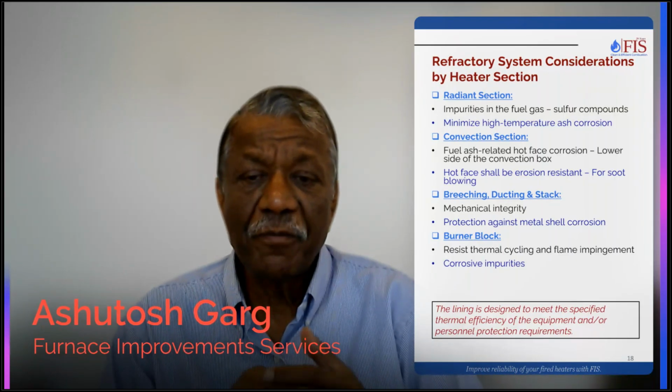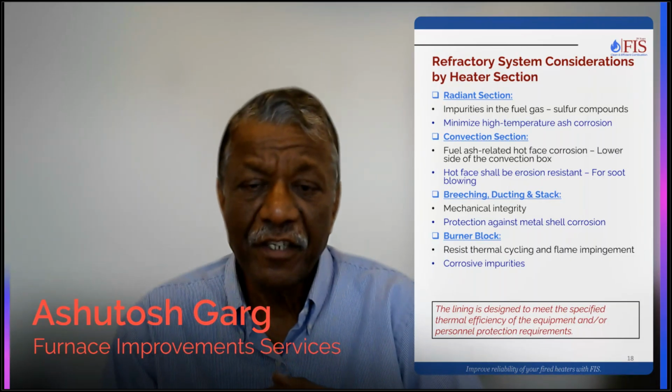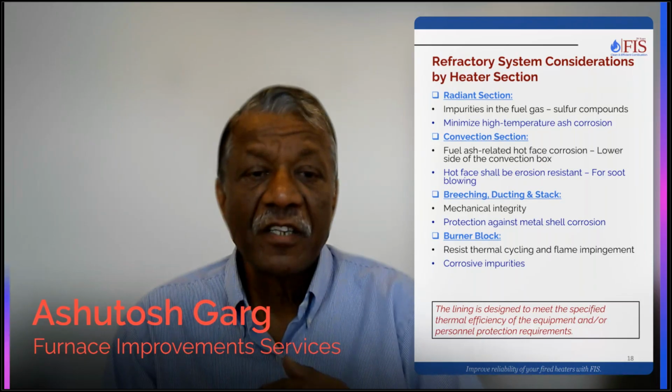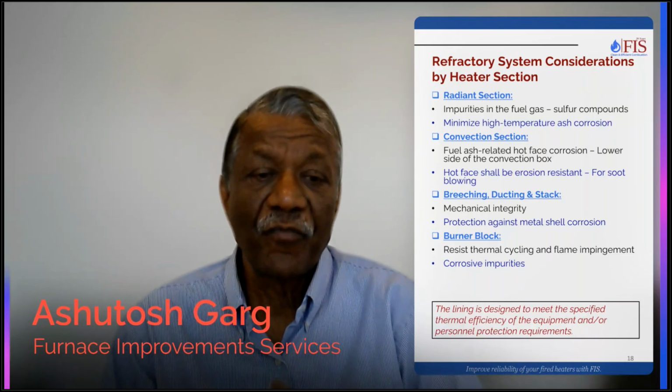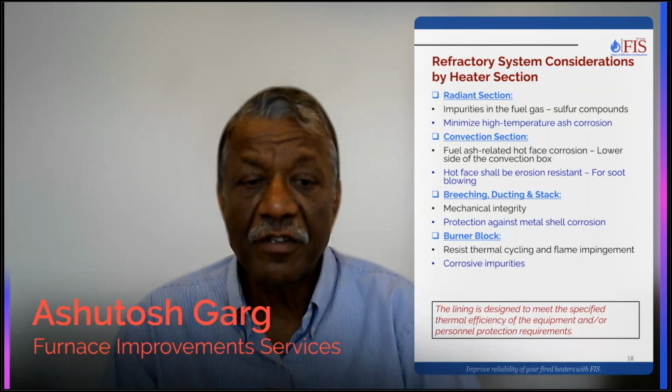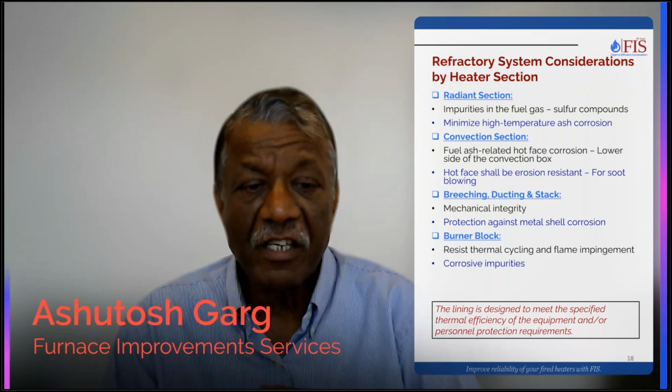Now, when you come to the convection section, if you have soot blowers for any reason, then that requires a special refractory in that area. Then we have burner blocks, because they are high temperature, so you need very, very high alumina refractory over there.